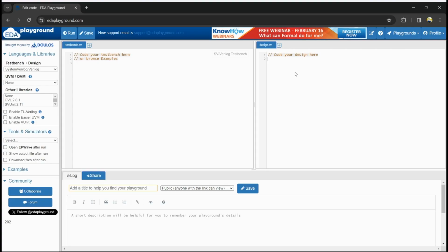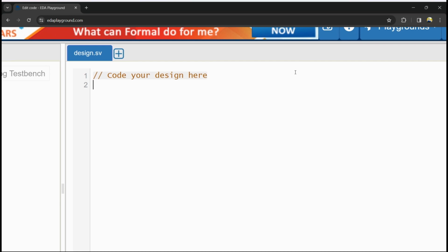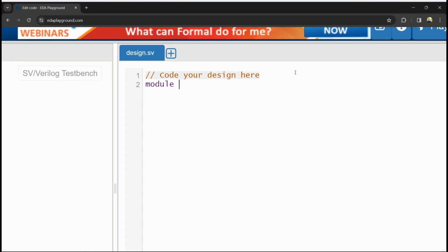Okay guys, now let's start making the Verilog code for the 4:1 mux. For that I am creating a module with the name mux, module mux. We are going to design the 4:1 mux, right? So we require four inputs, each having a 4-bit size. So I am defining 3:0, that is 0 1 2 3, it is 4 bit. How many inputs are required? 4 inputs, so a comma b comma c comma d, and we require two selection lines, right?